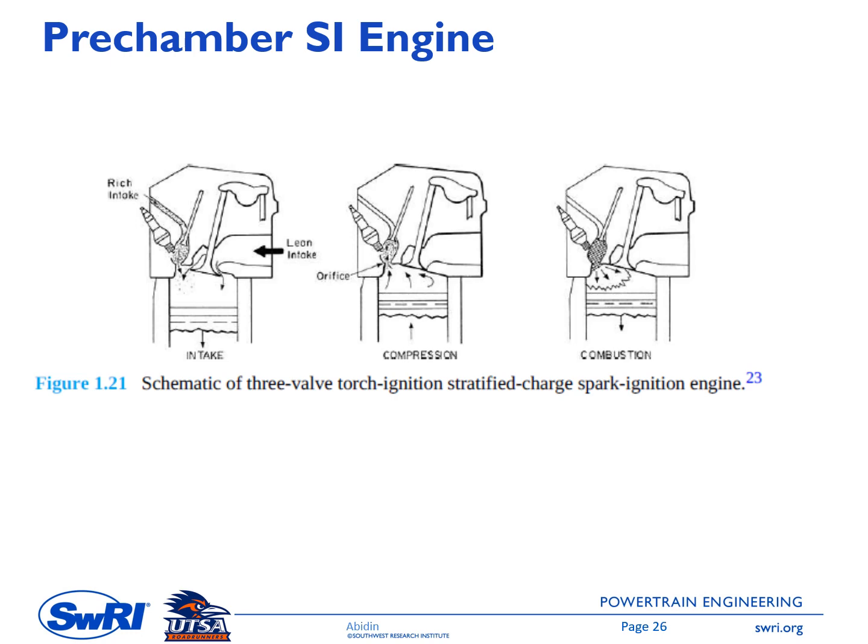Okay, so this pre-chamber is used to enhance the ignition process, and it is usually used when we operate the engine under lean conditions. It means we have more air, so we get better efficiency, but a lean mixture requires a robust ignition process. Therefore, we have a pre-chamber here to improve the ignition process.